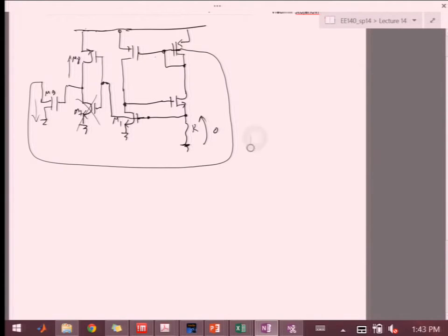And as it pulls that voltage, that's actually this voltage, as it pulls that voltage down, there will be now a VGS here that is greater than the threshold voltage, and you're going to start conducting some current. As that current is non-zero, on this R, it will start developing some voltage here.